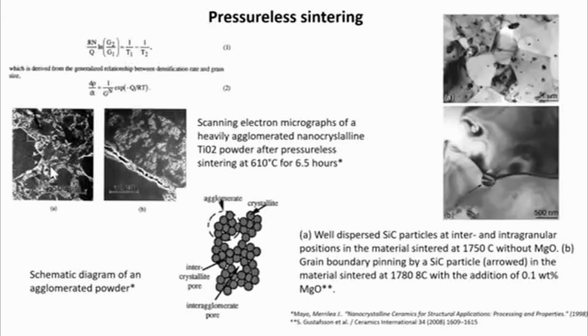If the agglomerates are micron-sized, one obtains very large, micron-sized pores. It leads to a requirement for high sintering temperature. To avoid the problems of uncontrolled grain growth at high temperature and a high percentage of residual porosity, the composition of the ceramic material and modern sintering technology must be applied. For example, Gustafsson and colleagues investigated the fabrication process of high-density pressureless sintered aluminum oxide with 5 volume % silicon carbide nanocomposites without special additives.